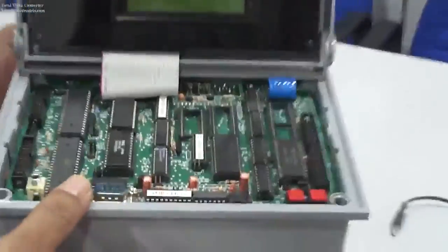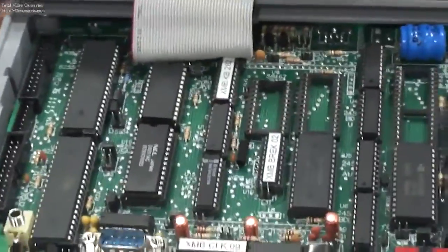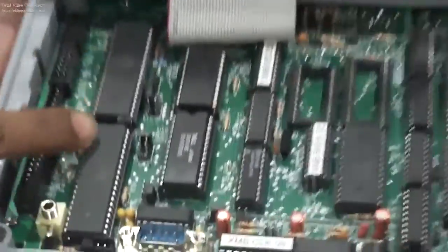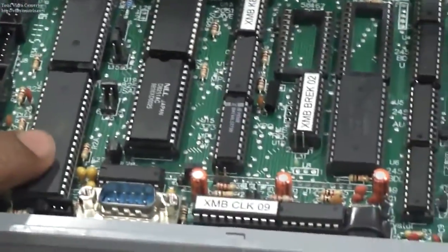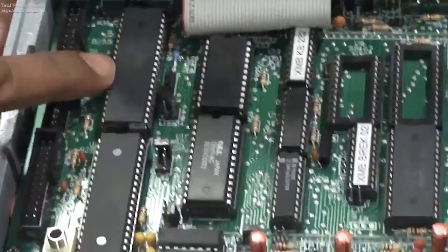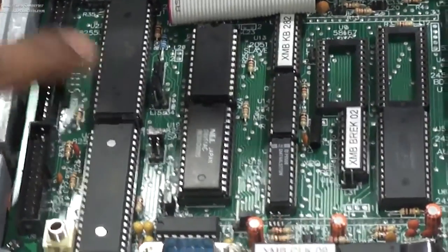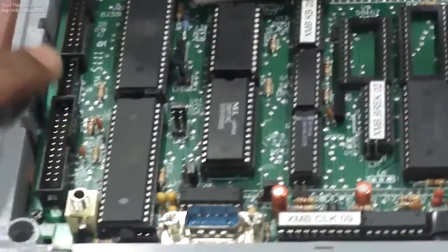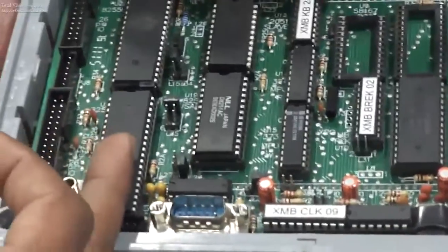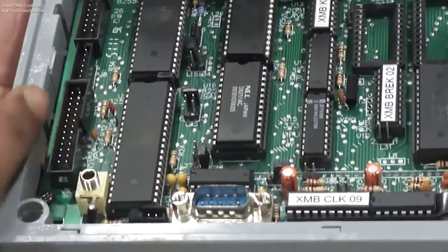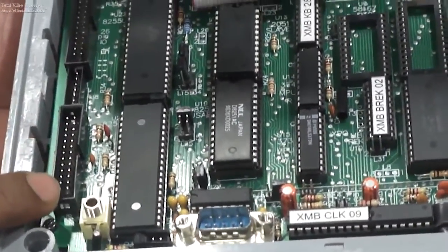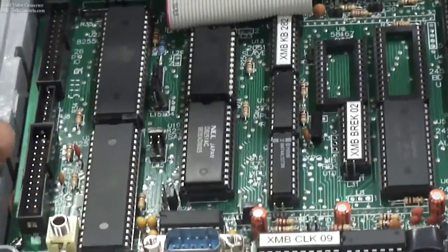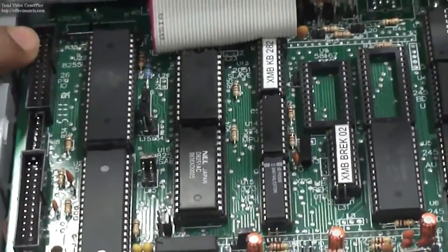On the motherboard section, we have to provide 8255 ports. Here we have provided two 8255 ports. This is the lower 8255 port, and this one is the upper 8255 port. These are the two 26-pin FRC connectors. The respective 8255 port pins come on this 26-pin FRC. This is for the lower port and this is for the upper port.